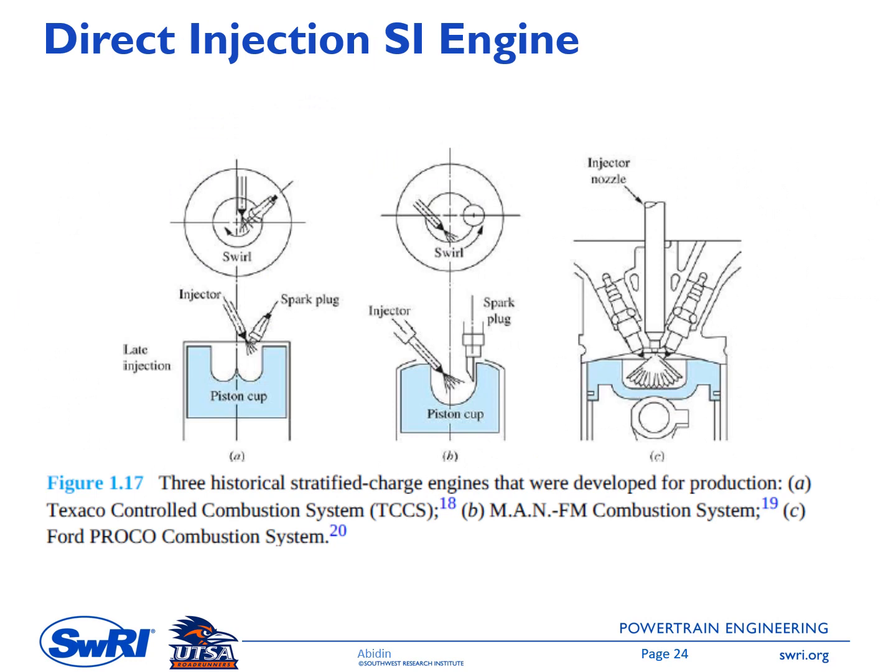Next one is looking at the characteristics of the direct injection spark ignition engine. To have a good mixing process between the fuel and air, we rely on the swirl flow, or the flow pattern of the air inside the chamber. We will learn this in more detail in chapter 7 about swirl flow, tumble flow, and so on. This is an organized flow, kind of like a big flow following a certain pattern that can be used to enhance the fuel-air mixture.